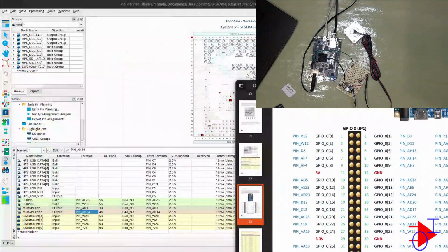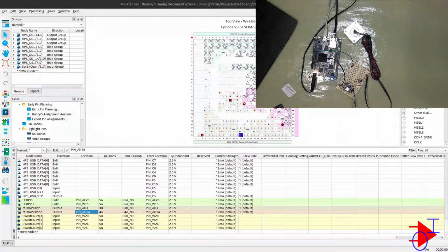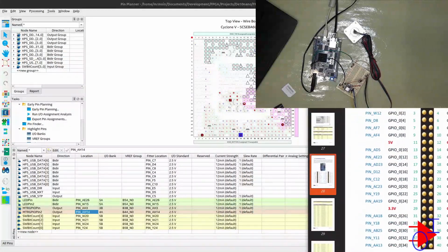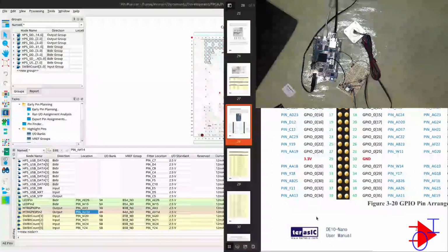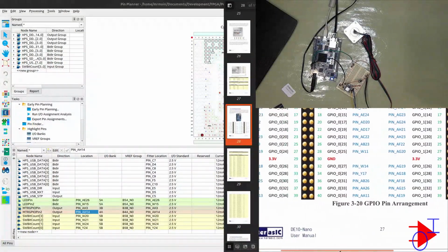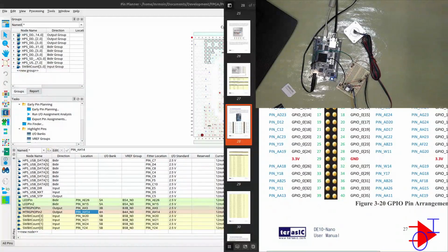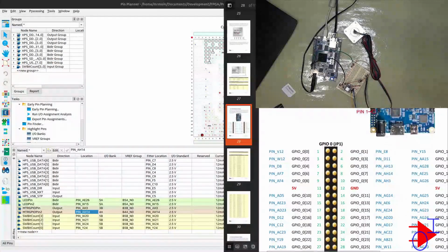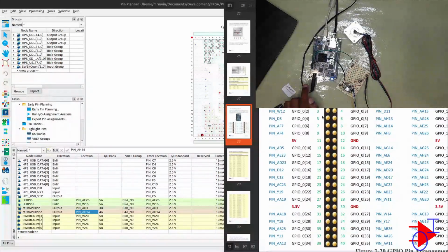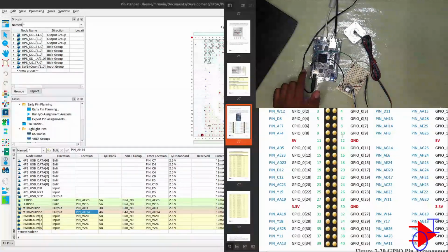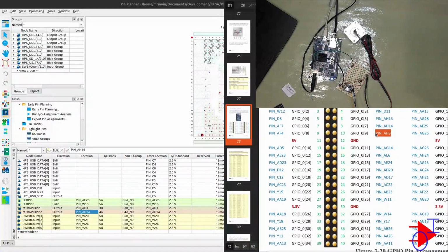So okay, this is a good reference. Let me pull this up here. Okay, now GPIO 0. GPIO 0 is the one next to the power connector, which in our case is right here. And in GPIO 0, we are connected to 12 for the ground. The next pin over, the one that's working, is pin 10, AH3 right there.